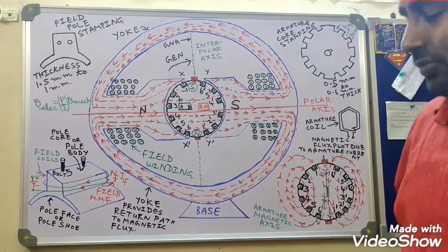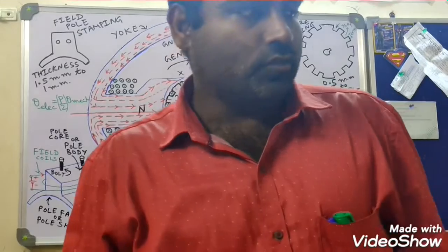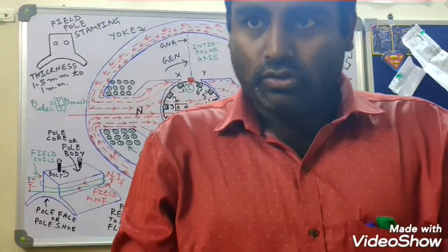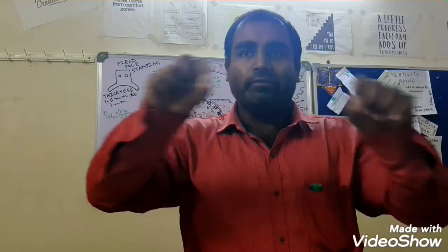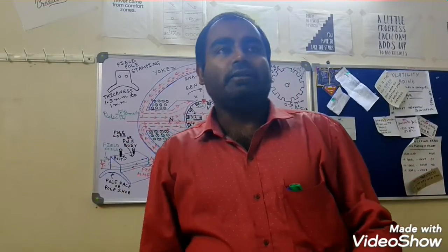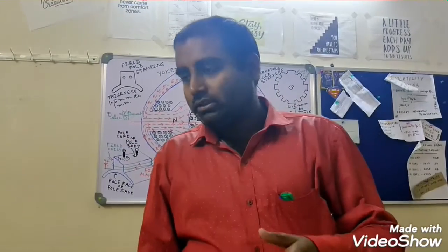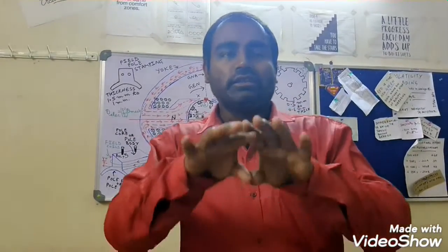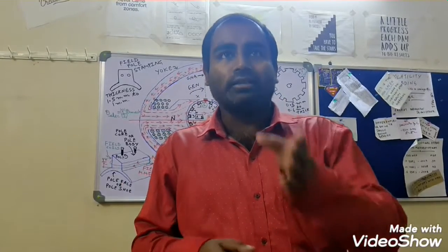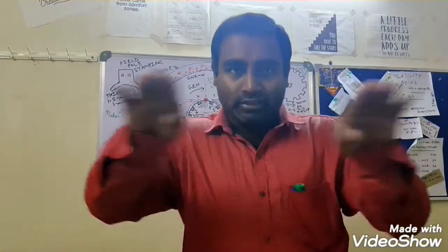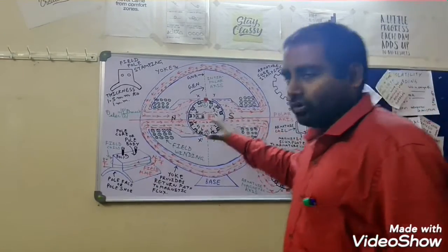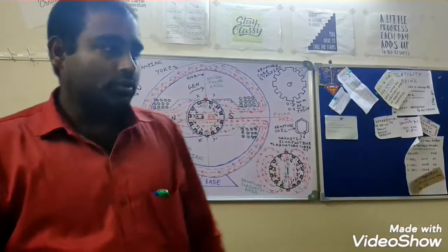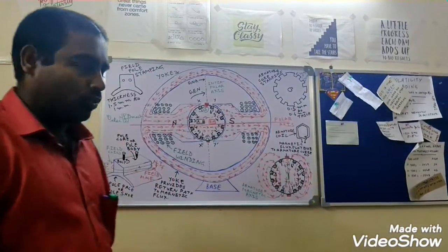Let's say you have a circle. What is the develop view? You cut the circle at one point and straighten it, so it will become a line. If you have a structure which is a cylinder, what is the develop view? You cut the cylinder at one point and then make it flat or straight. But before we take the develop view, let me tell you one or two points.